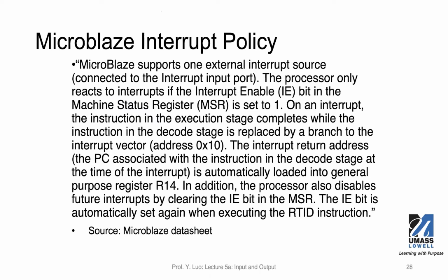Okay, one more slide about MicroBlaze. Again, don't take this as something that you have to remember. This is just saying that this particular microcontroller supports one external interrupt source. So you can imagine that physically, this microcontroller has one pin that can be used to send an interrupt signal into this microcontroller.